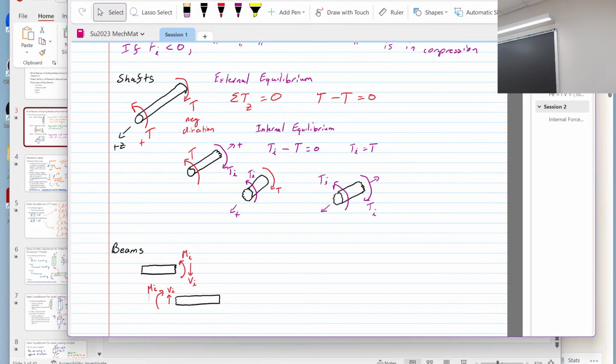And this is like springs in series. I'm applying an FR, and if it's springs in series, the force FR is the same inside this member as it is up here, because they're in series with each other. Or you can think of this as creating an effective spring constant for this whole beam that is experiencing an FR, and I want to know what the displacement is.